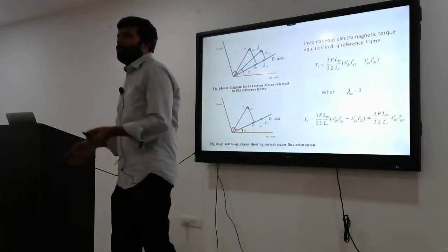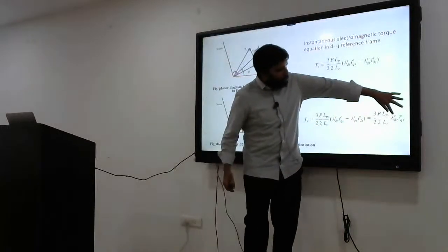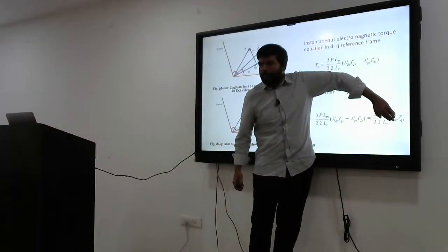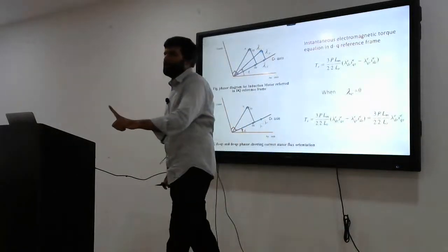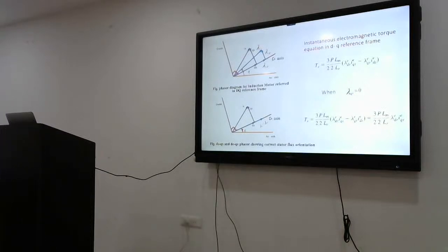Right? So one more thing: by maintaining the rotor flux as a constant, what will happen? Your torque equation becomes first order. You can think this is the beauty of the controller. Finally, your 3-phase induction motor torque equation will come into first order after adopting transformation plus orientation control.